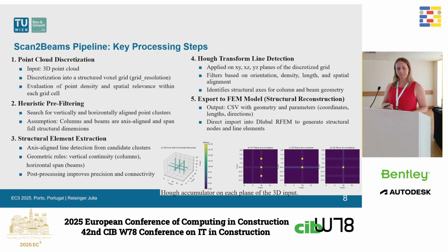And then we have this heuristic pre-filtering, searching for vertically and horizontally aligned point clusters with the assumption that columns and beams are always axis aligned and span full structural dimensions. And for the structural element extraction, we incorporate a process which leverages the geometric information about the configuration of the industrial skeleton.